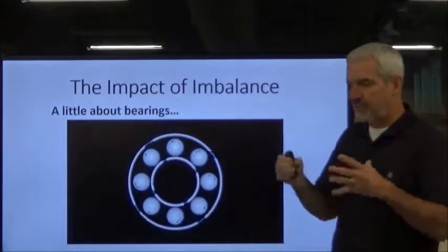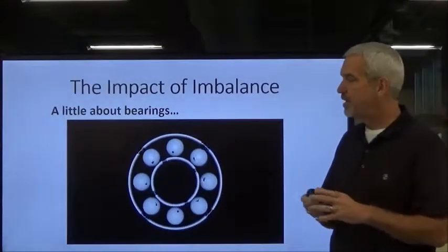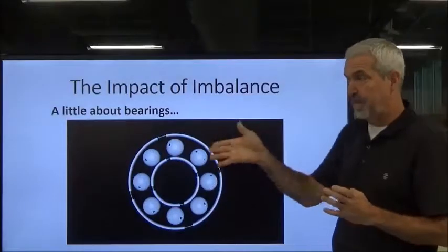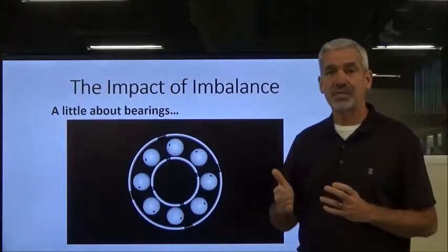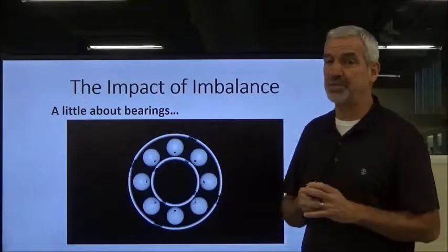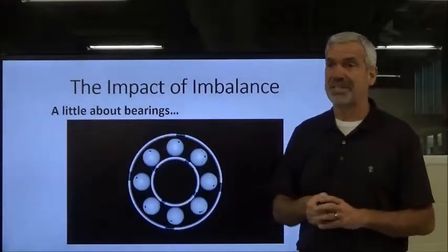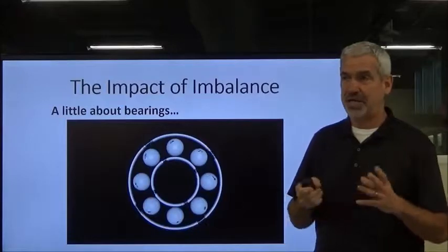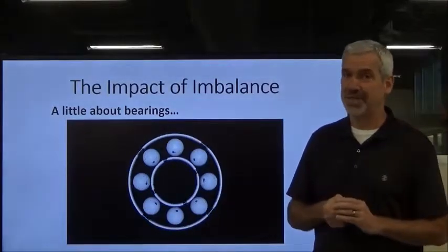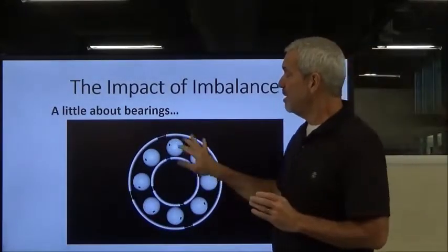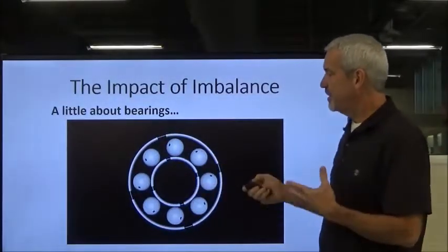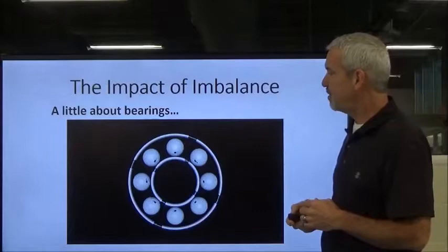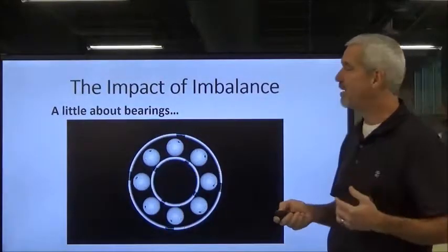So when we say we have a bad bearing, a lot of times with that particular bearing, I was able to dial in and show that the outer race was damaged. I didn't know why it was damaged until we cut it up and found out. But I was able to say the outer race is bad. And we cut it up, and sure enough, it saved my skin because, like I said, those mechanics were ready to string me up. But it turned out to be true. So anyway, just to let you know, several vibration frequencies could be at play within a bearing.